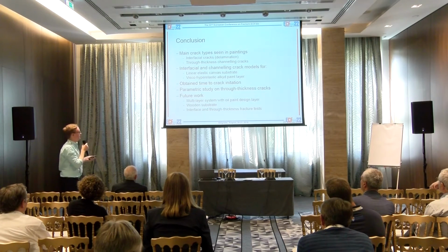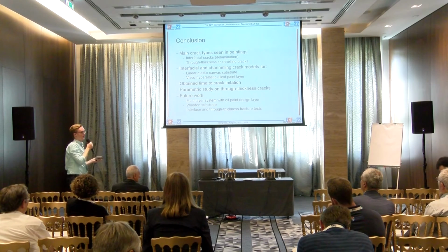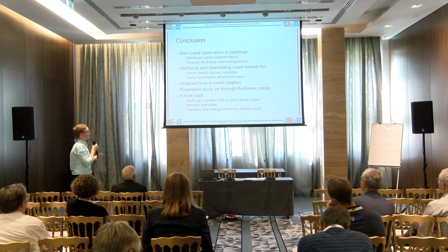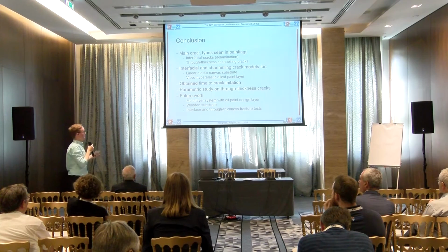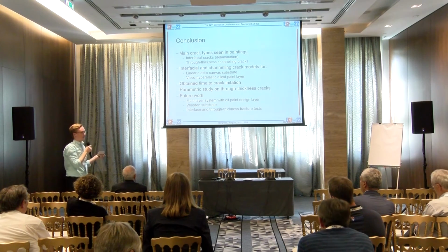And now we've just started to expand the models to consider multi-layers on top of the substrate, and also a wooden substrate, which increases the complexity of the model considerably, because it depends on how the wood's been cut, as I previously said. And then we're going to perform fracture tests in order to obtain the fracture energy for the interface and the through thickness.